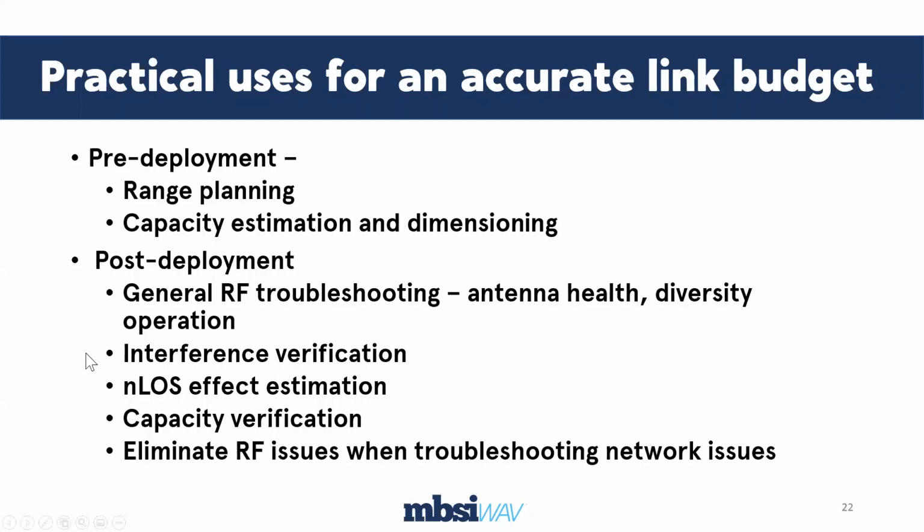If I'm receiving interference, sometimes I don't know that I'm receiving interference, but the equipment behaves as though it is. So rather than jumping up right away and changing frequency and seeing what happens, I can run my link budget and know the difference between the performance I'm getting and the performance that I expect, and from that number, I can tell if it's interference or not.